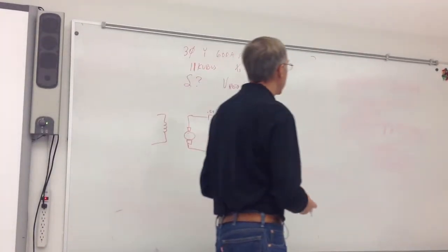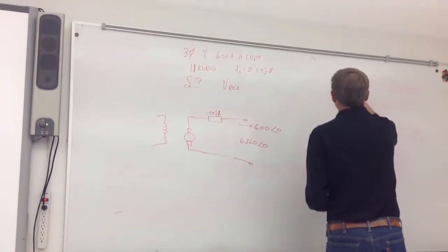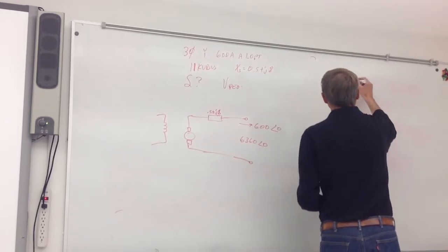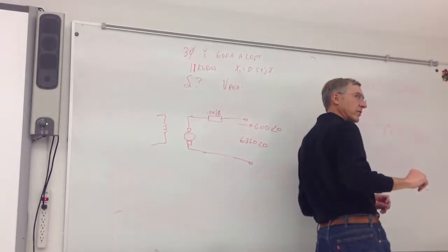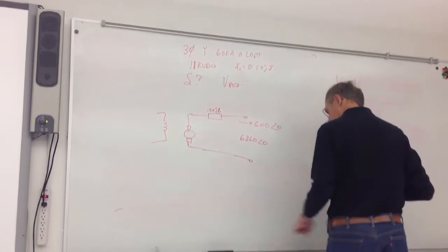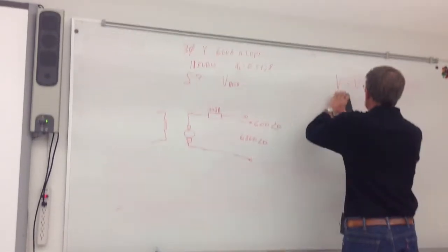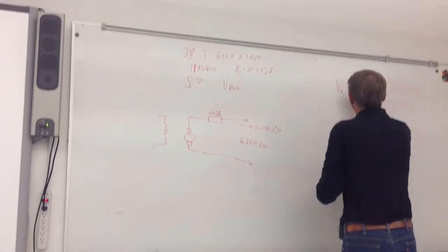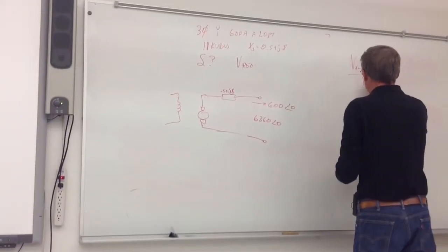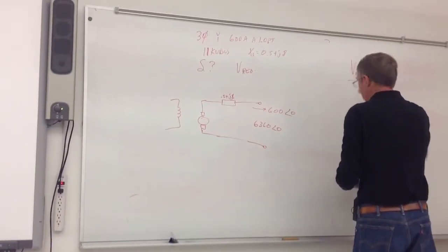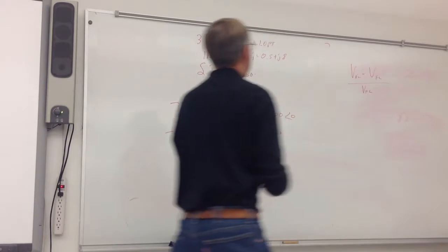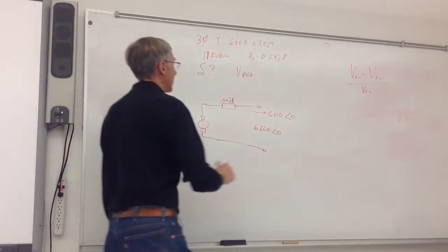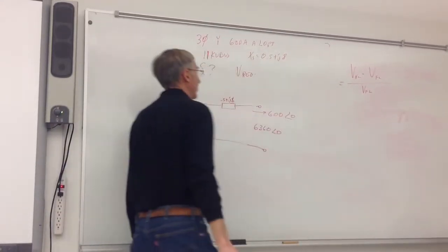No load minus full load over full load. V no load minus V full load, over V full load, right? Okay. So that's the voltage regulation, I think, that we're trying to find.